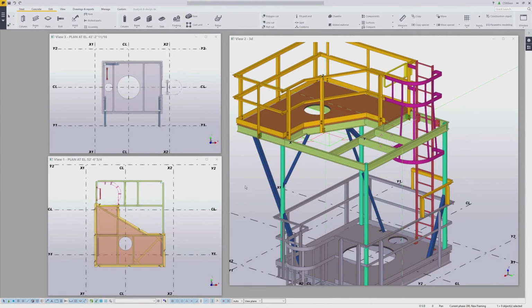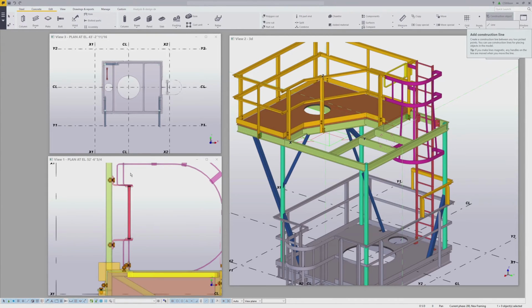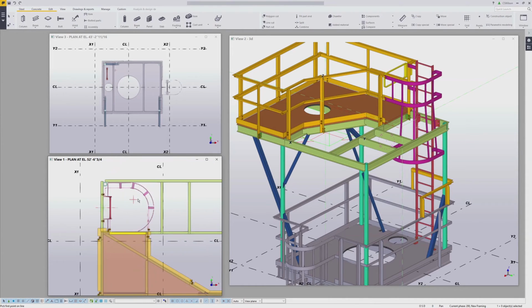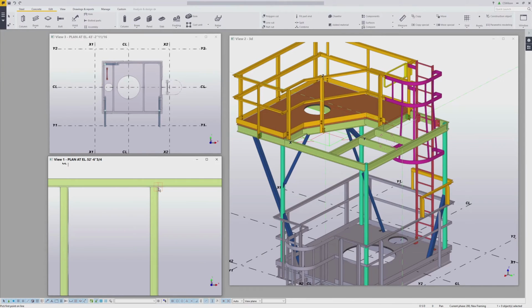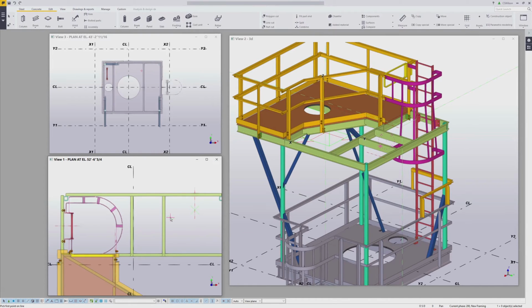To start, I want to draw a couple of construction lines. So the first one will be from the center of this rung perpendicular to the back of this framing member. And the other will be, I'm going to give a control click here and go perpendicular 1'8", give a point there, and then perpendicular point here. Now that I have those, I'll use the move to another plane command to actually move and rotate the ladder. This is a command I use a lot, and I found it to be very useful. You'll see me use it again when I model the railing.